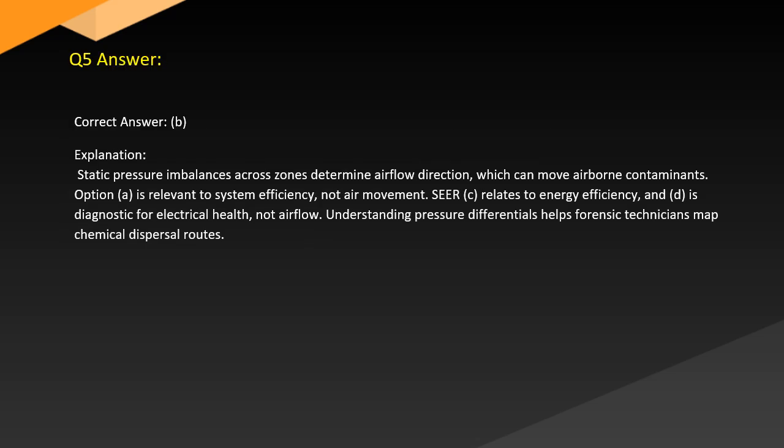Answer. Correct answer: B. Explanation. Static pressure imbalances across zones determine airflow direction, which can move airborne contaminants. Option A is relevant to system efficiency, not air movement. C relates to energy efficiency, and D is diagnostic for electrical health, not airflow. Understanding pressure differentials helps forensic technicians map chemical dispersal routes.